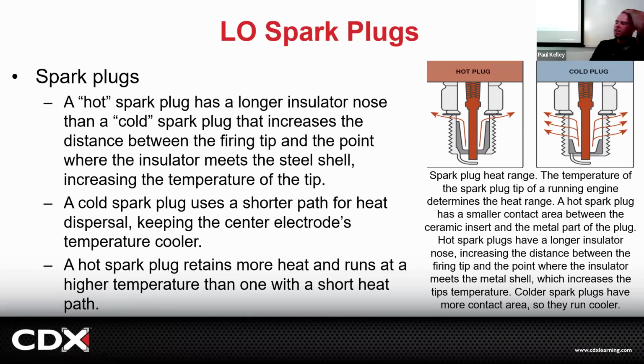Now there are times where, if you're going to run nitrous or some high performance, you may go with a 1-step colder plug, but that's not per the manufacturer. That's more per the tuner with the experience. So because we're mostly concerned about repair, we're going to run OEM spark plugs. But at least now you can visualize one of the numbers on the spark plug is the actual temperature. And if you're too cold, it won't self-clean and you'll wear them prematurely. But if you're running the spark plugs you're supposed to, and it's OEM, they should last as long as the maintenance interval and maybe more.